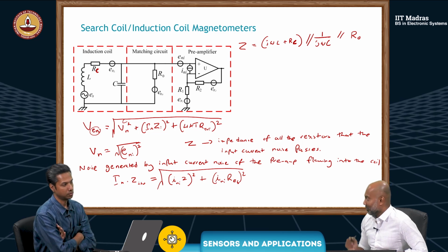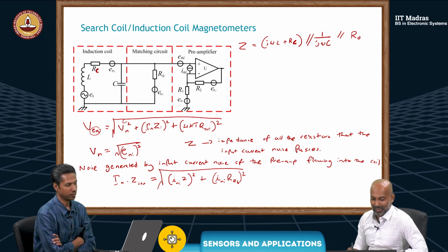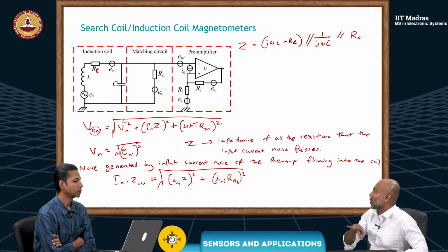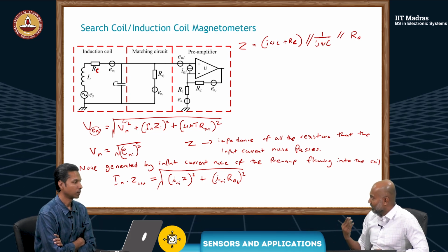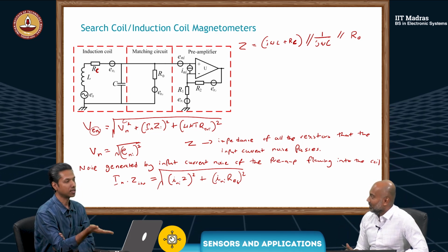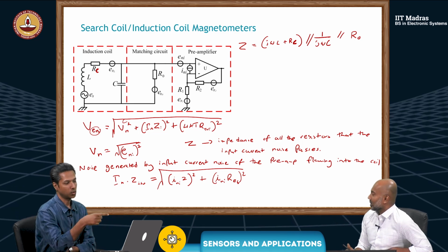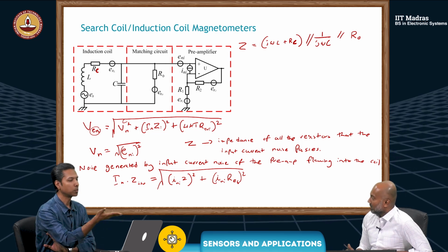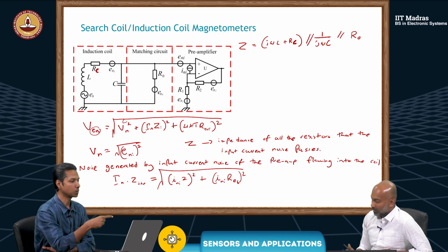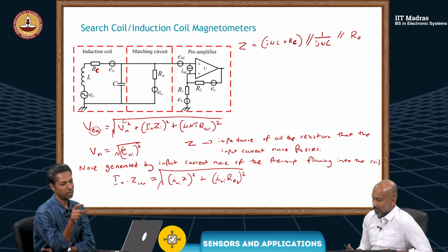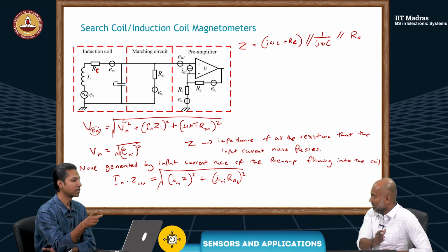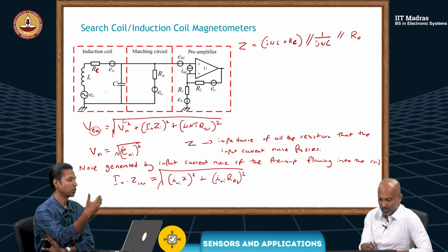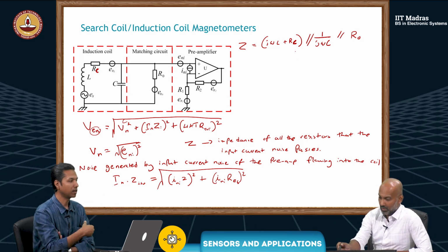I think that's a very good point, because you can very easily be confused if you don't know which way to look from. So maybe we can consider this Thevenizing the circuit. All the sources will be replaced by their internal resistance. These are voltage sources, so those will be short circuited. And then from the output, in this case, it's across R0. I look from that side, and R0, then 1 by j omega C, and RC plus j omega L, all of them are parallel.